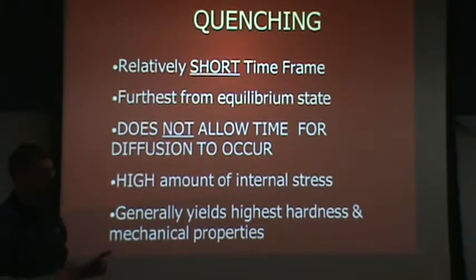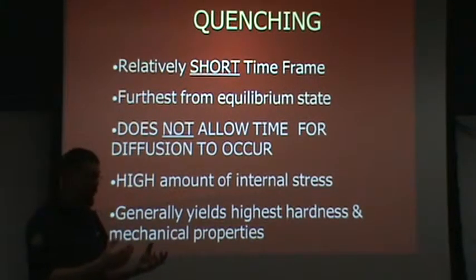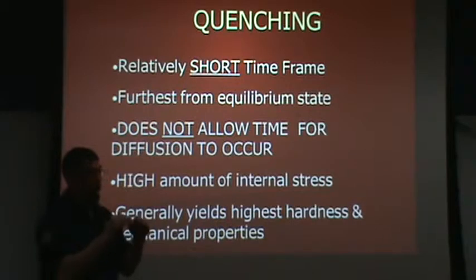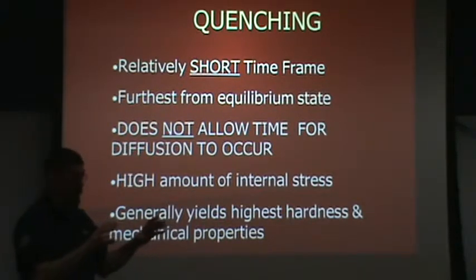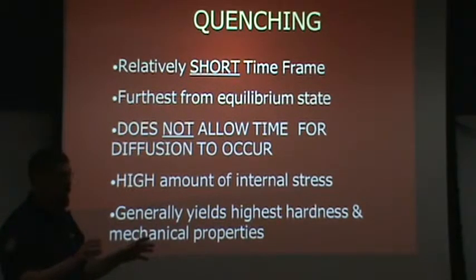So, a few different things we want to try to address in that question. First part, if I have different hold times at the same temperature, do I get different grain sizes? Right, that was kind of the first part of your question. Well, you don't, because you haven't dissolved the grain pinners. Grain pinners and their distribution is what fixes the grain size. So as long as I stay at a temperature where they have the same number and distribution of grain pinners, grains won't get any bigger.